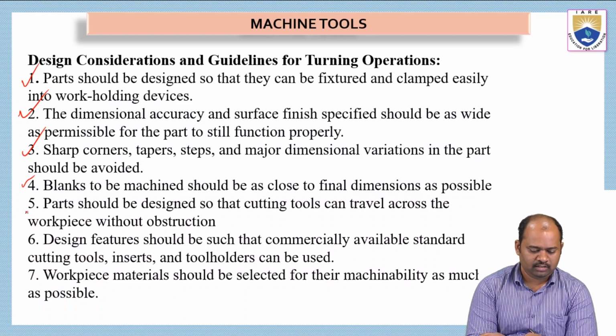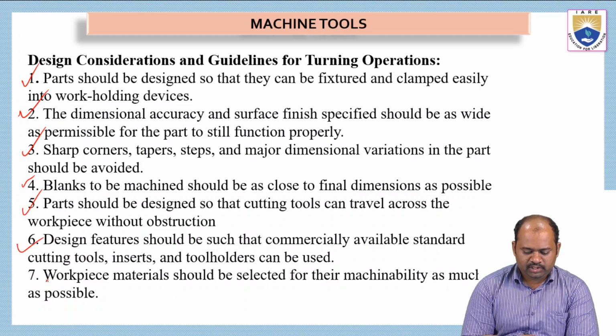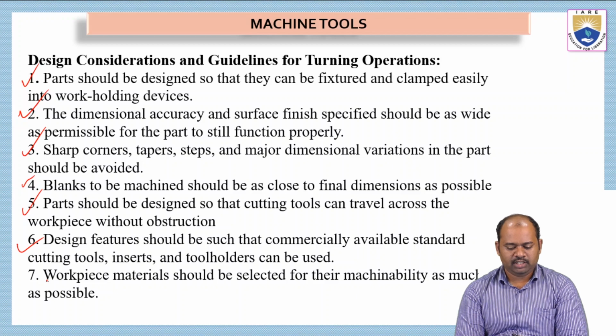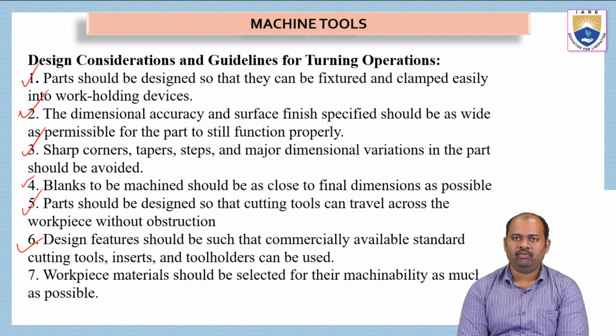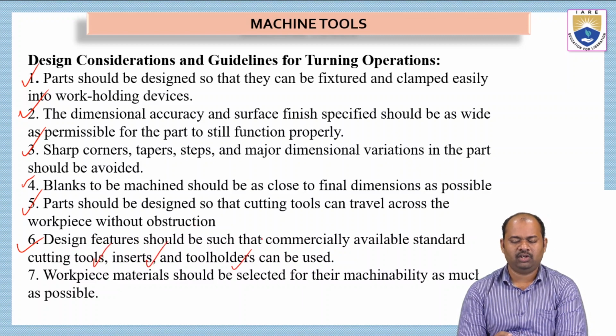Okay. And then design features should be such that commercially available standard cutting tools, inserts and tool holders can be used. This is a very important point when you design a workpiece which is to be machined on a lathe machine. So you have to follow standards. Otherwise, cutting tools, inserts and tool holders cannot be found.